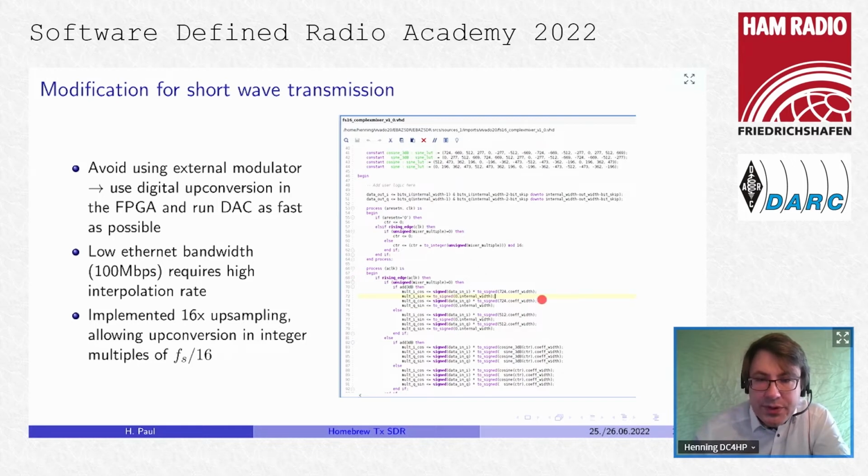It's really simple. It's just a pointer going through this lookup table, and the pointer increment tells you how much you upconvert. If you increment the lookup table by 1 with every input sample, you just upconvert to the input sampling rate, meaning 2.5 megasamples if you use the 40 megasamples output rate.